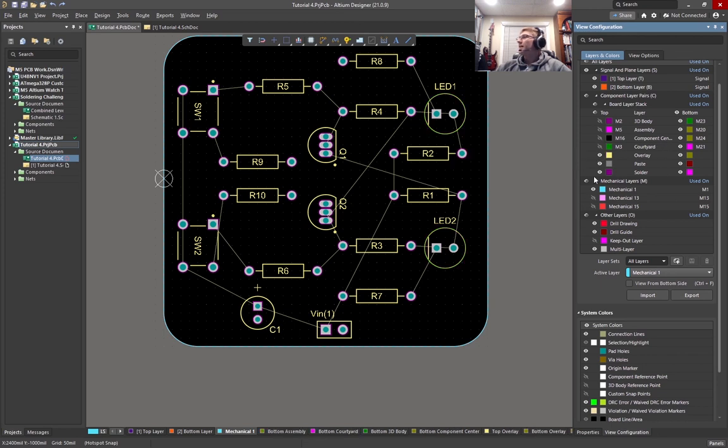Courtyard. So as I do this, there's not going to be solder paste. So as I do this, this bottom panel is going to get shorter. And for right now, I'm actually going to hide everything in the bottom layer. I can do that by just clicking this button right here, and that's going to take out most of that layer.